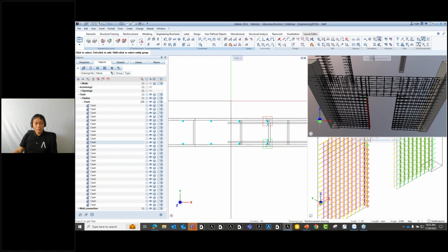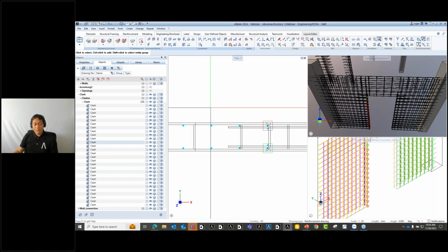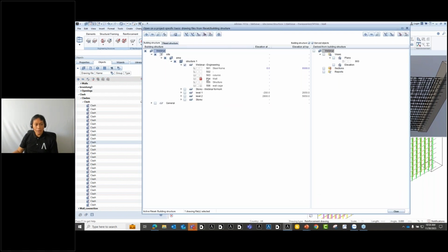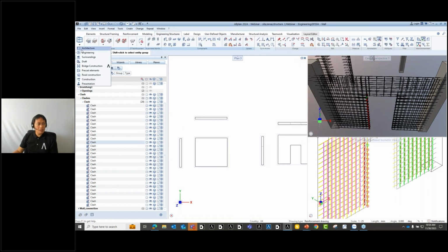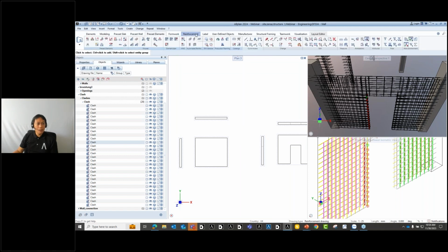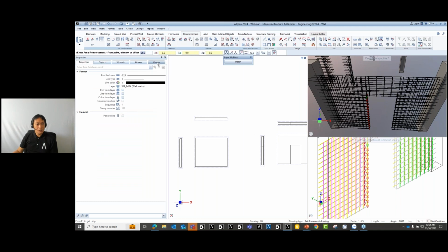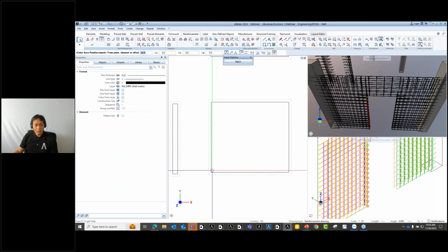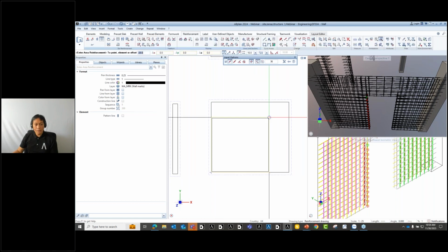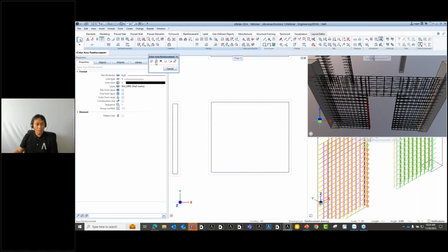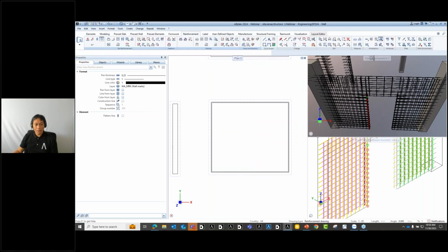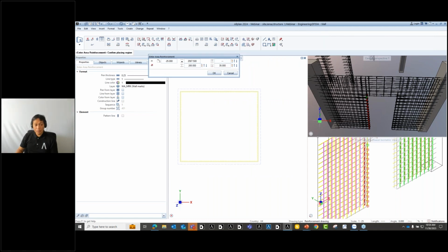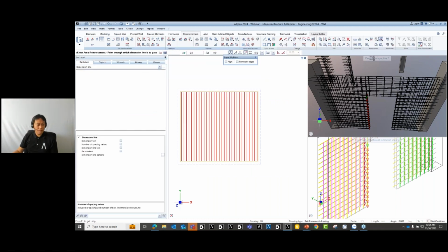So we go now to the mesh welding system, and how to optimize it. We can go to our small wall here. I already have it here. Then I can create a very fast reinforcement. I will go to my precast element, then my reinforcement, let's say mesh, this one, and select this. Or instead of selecting, I can select the area. So I can select this one, change it to 35. So I will just create a very fast reinforcement.